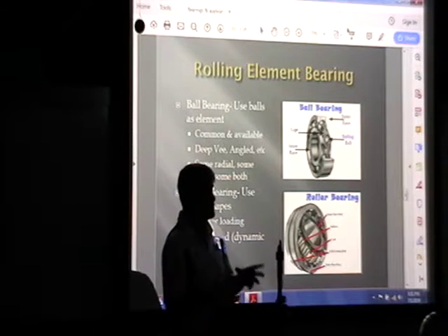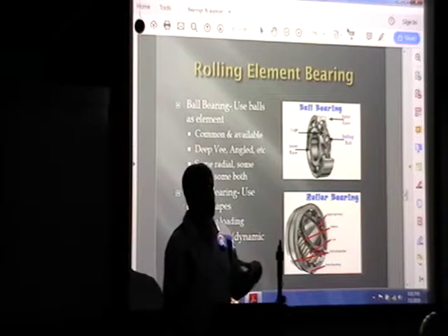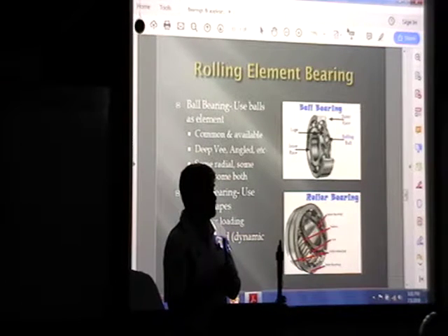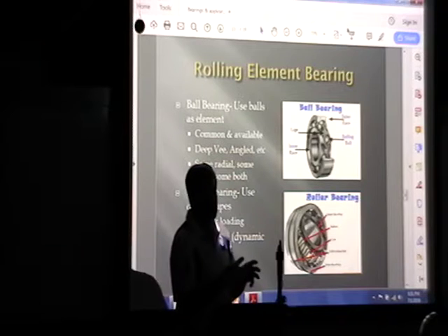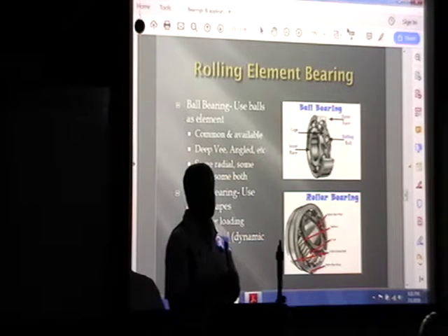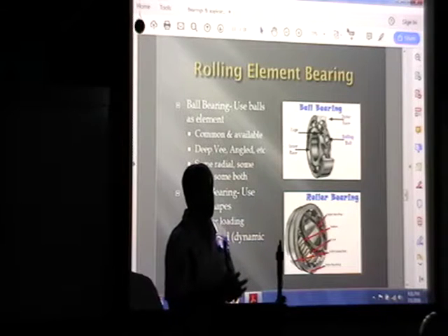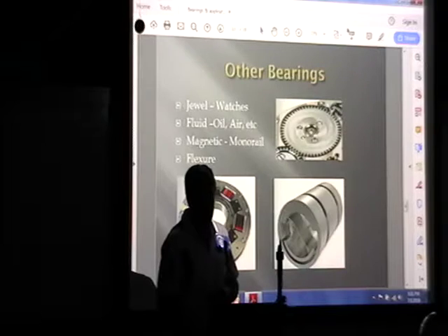Every manufacturer has a standard way of doing that. And a lot of them are common. I mean, you can usually cross-reference an SKF bearing with a Timken bearing and that kind of thing, but they really don't rate them or size them by ball bearing size. Typically, it's a construction method or a speed rating that the ball bearing has, because there are maximum RPMs for different sizes of bearings too. Okay. All right. Is that how it's what you're asking? Yeah, more or less. All right.